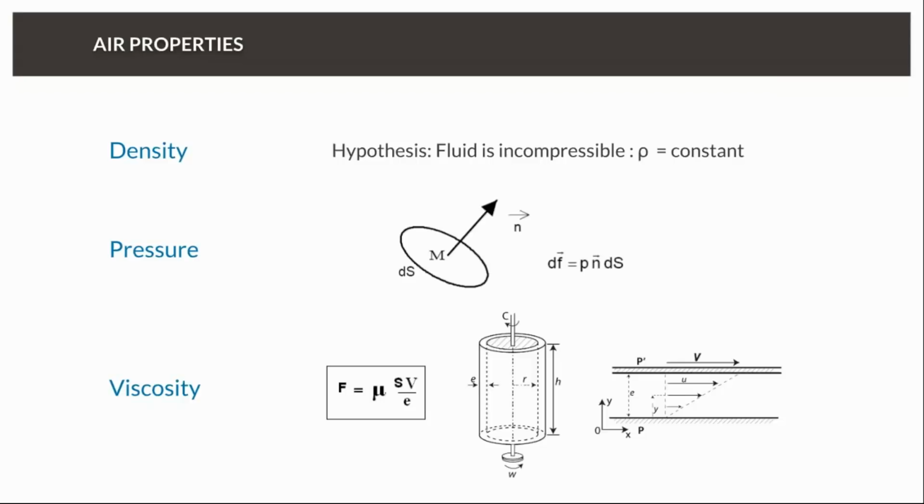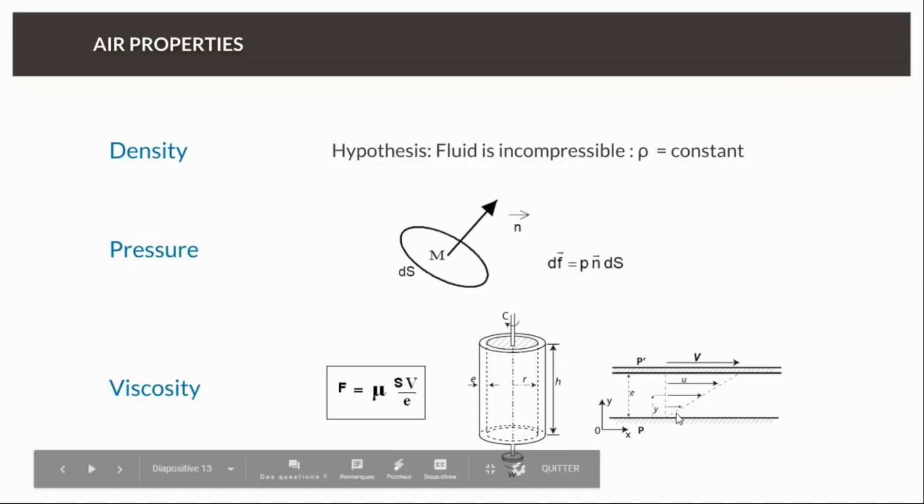And to illustrate in a different way the Couette experiment, this cylinder rotating inside a bath of viscous fluid, you could unfold the cylinder as an image. Then you would have one wall, for instance on the sketch, the bottom wall would be the fixed wall, and you have a top wall moving at a speed of velocity v. So it has a differential speed between the non-moving wall at the bottom and the upper wall moving at speed v, and so you create a gradient,